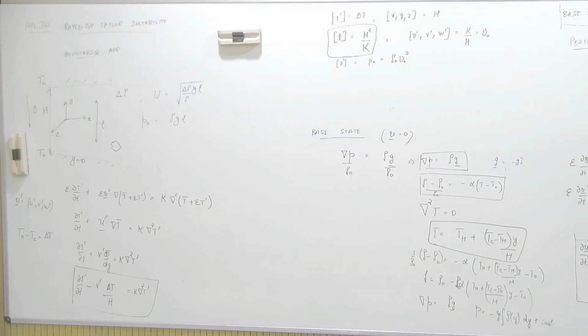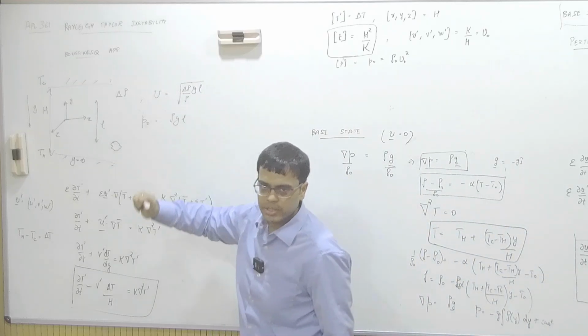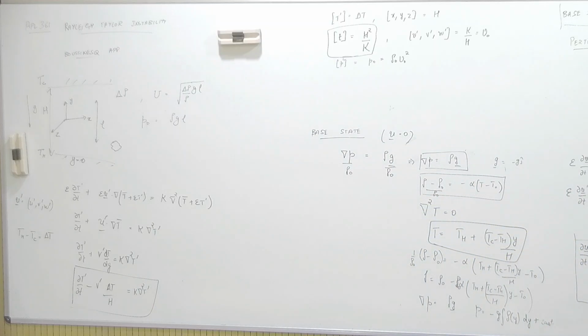Each of them mean different things. If you define it using momentum diffusivity, then instead of temperature, you are saying, oh, there is some velocity perturbation, how long it takes to diffuse this velocity perturbation. And there is no reason why that time scale should be equal to this time scale, because it all depends on this new parameter instead of this kappa parameter.